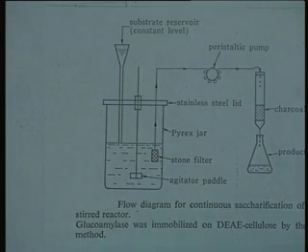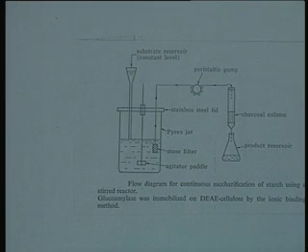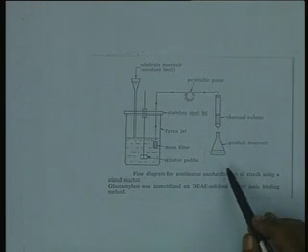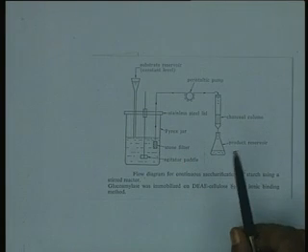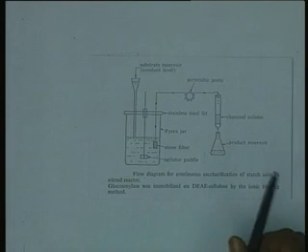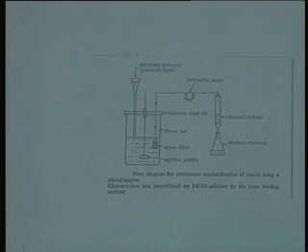This was the system reported for glucoamylase immobilized on DEAE cellulose by ionic binding. Again, DEAE cellulose is a very stable carrier which can be regenerated, although no such commercial process is operational in the case of glucoamylase, mainly because of the process economics. Even most of the processes which are in use are using adsorption onto clays, bentonite or some other clay, not any expensive or well defined matrices. So, these are some illustrative examples, not that these are the only processes which are operational.